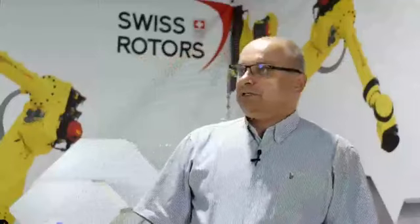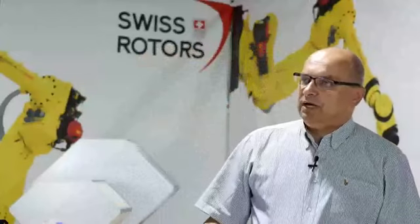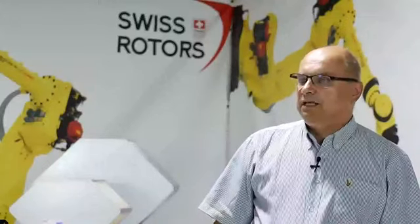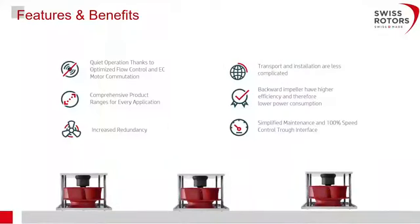And of course, the backward impeller has a higher efficiency than the forward blade impeller, so we have lower power consumption. And then due to this Modbus and the 0-10 volt signals, which can control the RPM of the fan, it's much easier to control the whole system.